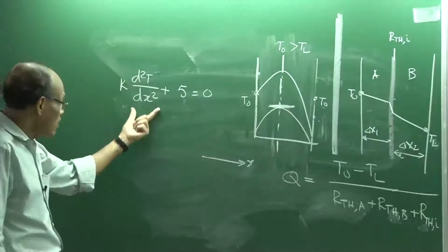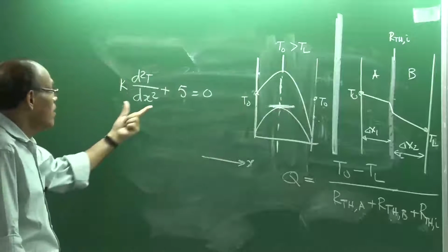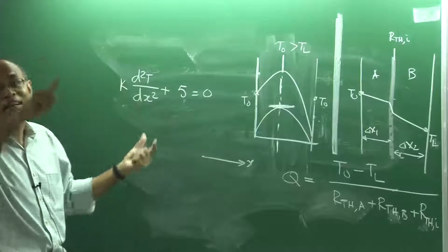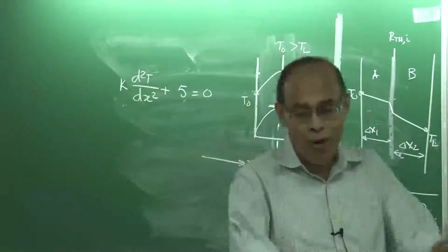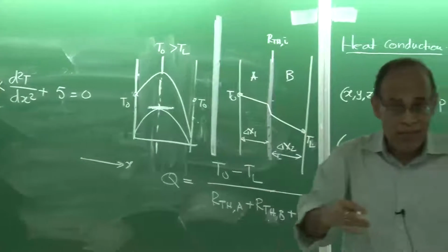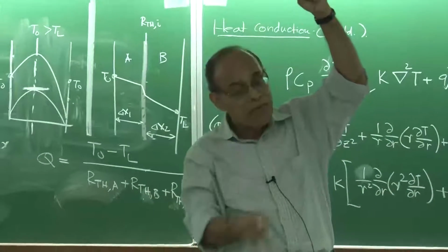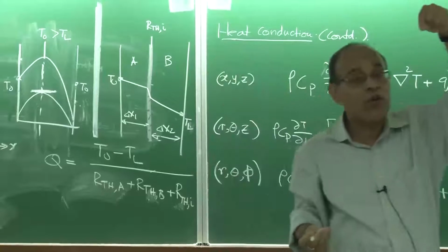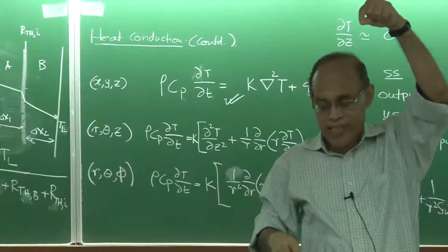So, therefore, once we solve this equation with unequal or equal boundary conditions, we will never get a straight line, but we will get a quadratic velocity profile, and that can be a very regular parabola, just like the pipe flow problem, provided we have the same temperature. Remember that when you have flow between parallel plates, we have the no slip boundary condition applied. So, boundary conditions on the two surfaces are identical.